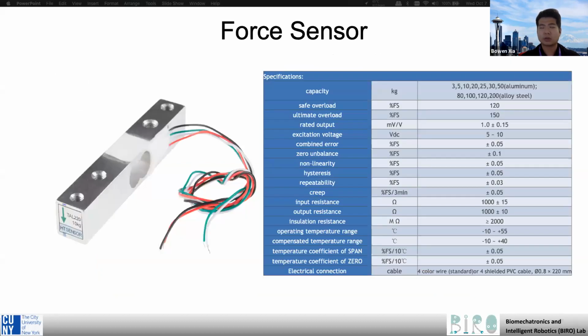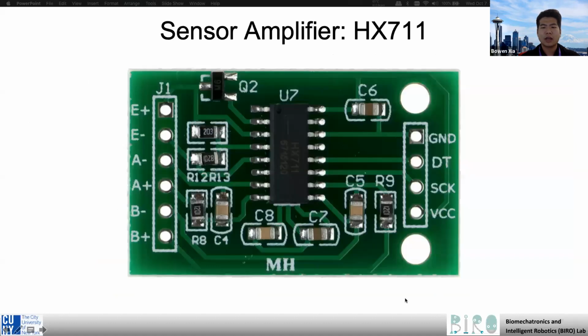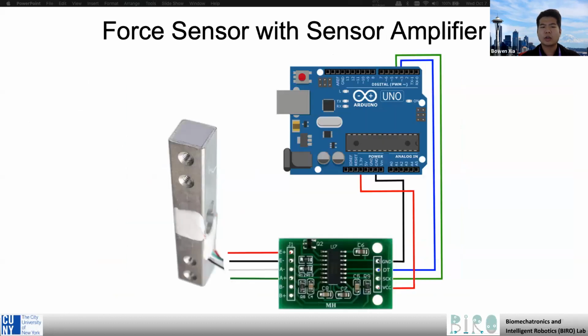A force sensor, it will be like this one. We will provide a 10 kilogram force sensor, and here are the specifications of it. And HX711, which is a sensor amplifier. We are going to hook up the Arduino Uno, the HX711 amplifier, and this force sensor together.